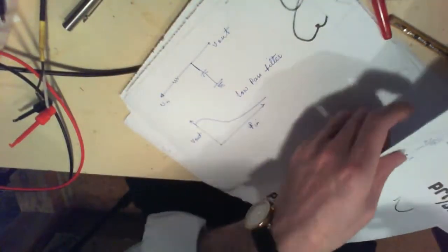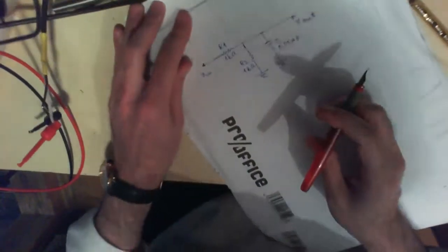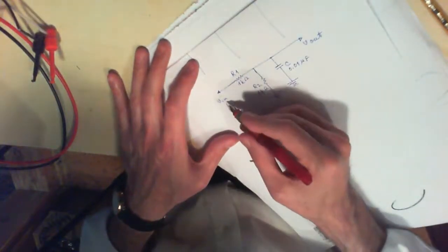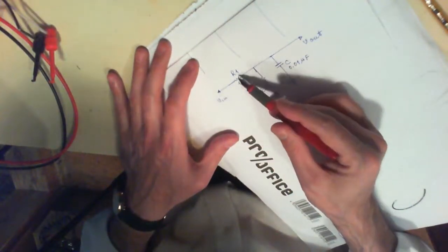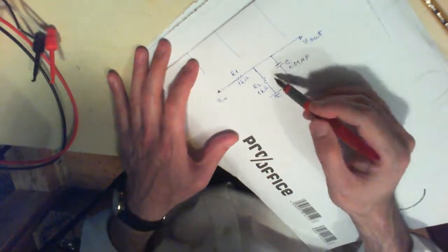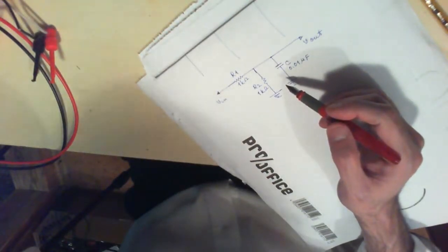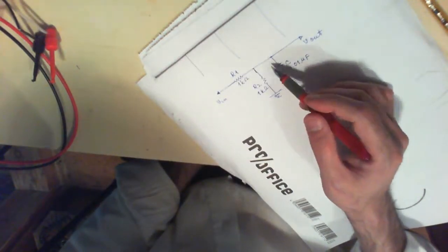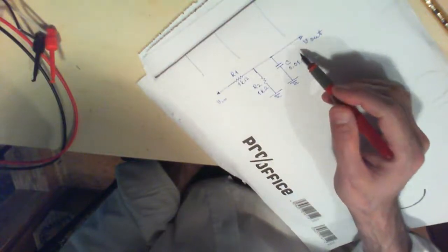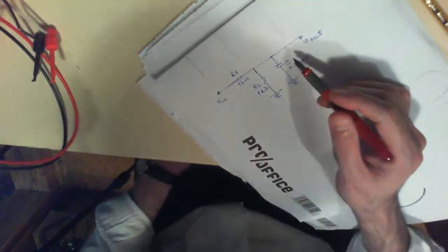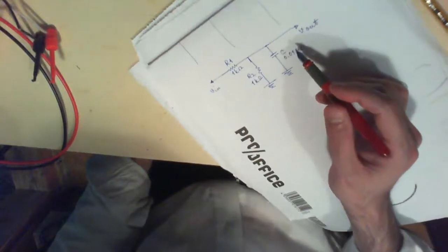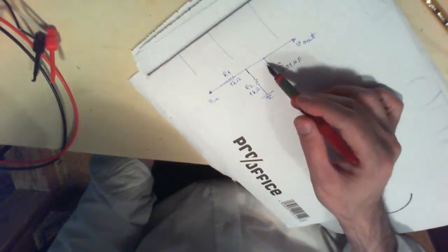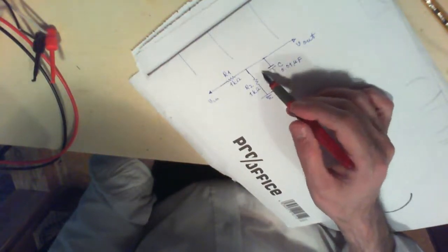Now the circuit that we have here is basically something like this. We have this V in, and then a resistor over here, and a capacitor. The interesting thing about this circuit is that it behaves differently for DC and AC inputs. If DC comes in, then of course DC is not going to pass through this capacitor.